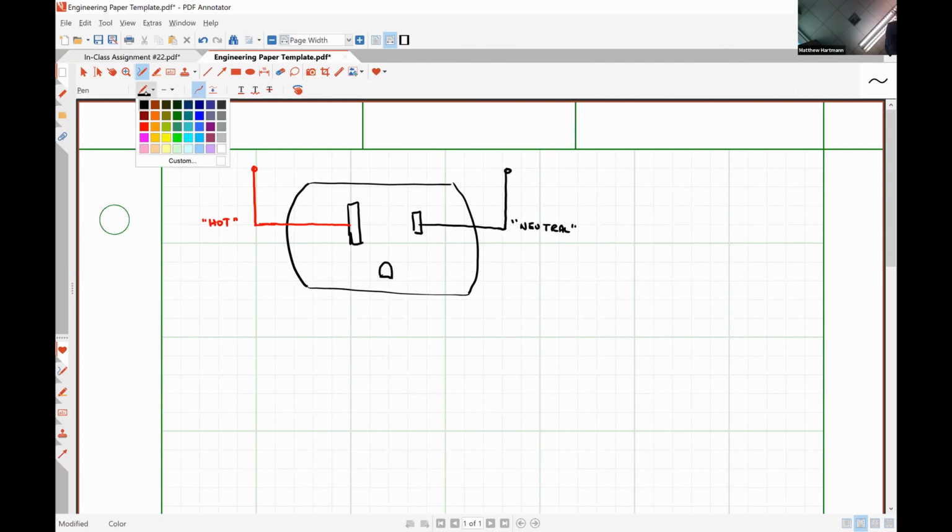And then you would see a green wire, and this is ground, like actually tied to earth ground. And that ground connection isn't really part of most circuits. It's an external connection to literally the surface of the earth through a metal rod driven into the ground. And it's a way to dump off excess energy. Outside of your junction box or your breaker box or whatever you want to call it, you'll typically see that your neutral conductor is tied to your ground. But inside your home, the neutral is a different thing. All right, so